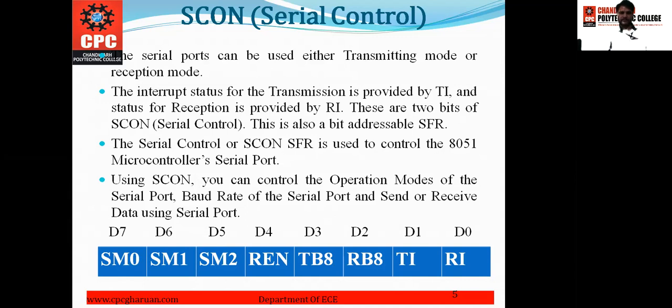The interrupt status for transmission is provided by TI, the transmit interrupt, and the status of reception is provided by RI, the receive interrupt.